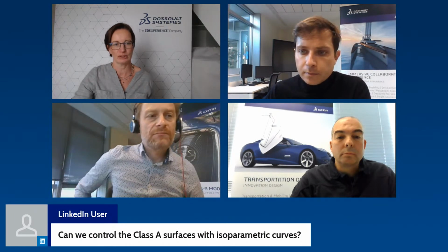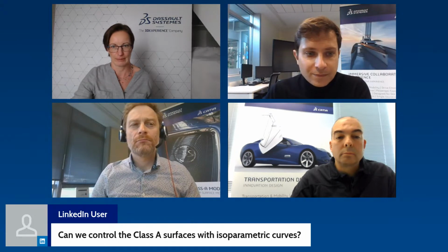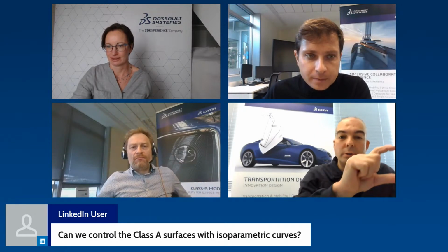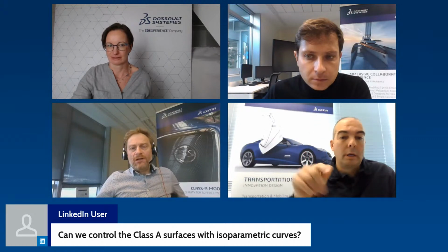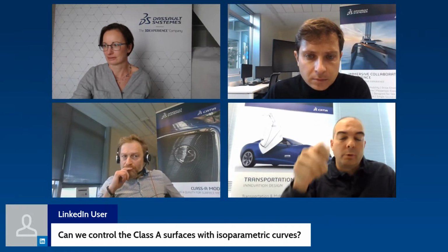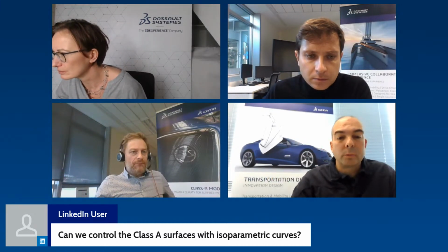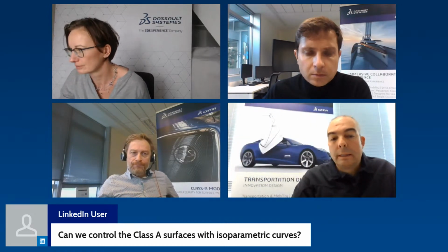Okay, let's go to the next one we have here. Can we control the class A surfaces with isoparametric curves? Yes, actually, that was the demo in Sylvain's part. A very interesting workflow is you get two guides, you create a section with an isoparametric curve, for instance, where you don't keep history, and then you can even use this curve to reinject it as a section of the surface to get an H sweep, for instance.